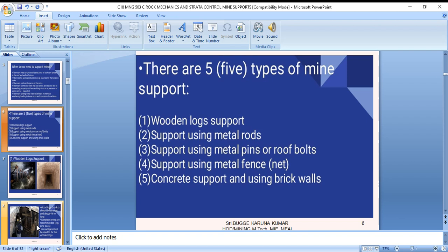So, research into strong, lightweight materials for underground supports has shown that the most promising one is glass fiber reinforced plastics. These have not been introduced in our mines. As tested in so many countries, Russia and others, precast concrete assemblies for support have also been tried and used in our mines. They have serious disadvantages: great weight and difficulty in handling underground.